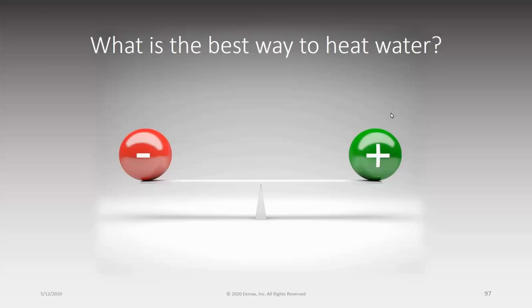How much of an impact does a large number of on-demand heaters, like the 150, play on the electrical load needs for the building? How many can you run at a time? There's diversity in plumbing, but there's no diversity in electricity. So if you're installing one, you've got to make sure it can operate. That's my answer to that question. Maybe there are different distribution methods and different panels, and maybe there's something a little bit above my head on the electrical side, but general rule of thumb, if you're hooking it up, you've got to be able to run it.